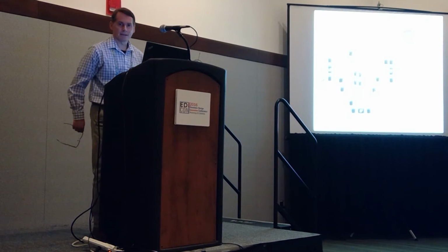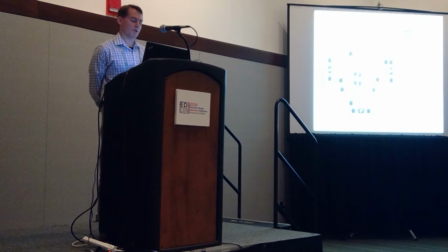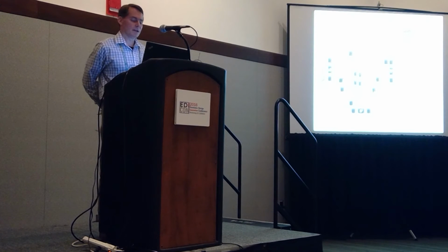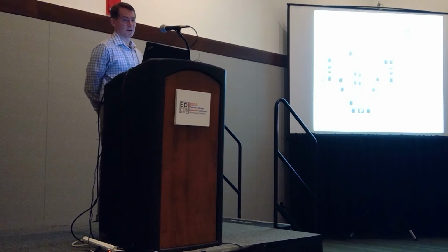Have you experimented with anything beyond Ku band at all? For the GaN mixers, no, we have not gone beyond Ku band. Part of the issue is that this process is what we like to call a landed metal process, so the air bridges are quite limited. When you land the metal on the substrate, you're limited in the frequency range of some of these components, especially the spiral transformers. This X-band design is about as high as we can go with the spiral transformers. The FET, we could probably go higher, but as that device gets smaller, we get a lot more conversion loss.